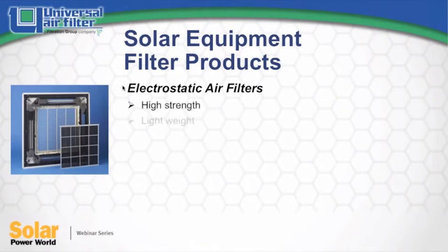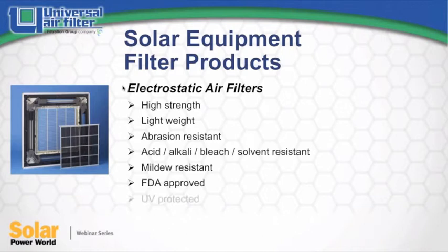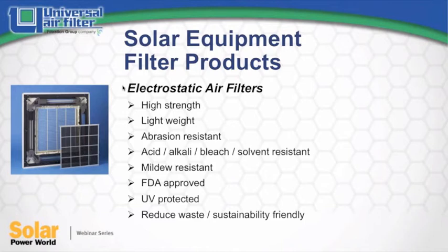Another durable product that's reusable and offers higher efficiency dust capturing is electrostatic media. Washable polypropylene mesh stands up to corrosive airborne chemicals. It's lightweight and delivers improved dust capturing over the all-metal filters.